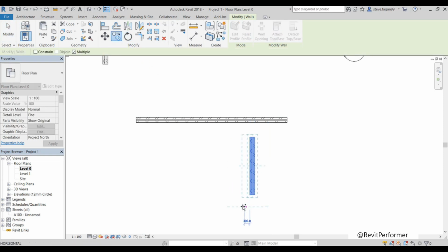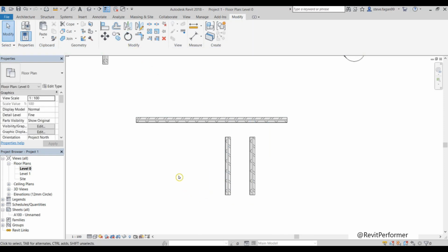I'm going to copy this over. So I'll select the trim and extend multiple elements. I'll then select the wall I want my lower walls to extend to, and then the walls that I want to extend. And then if I wanted to trim away that excess piece, use my trim and extend.